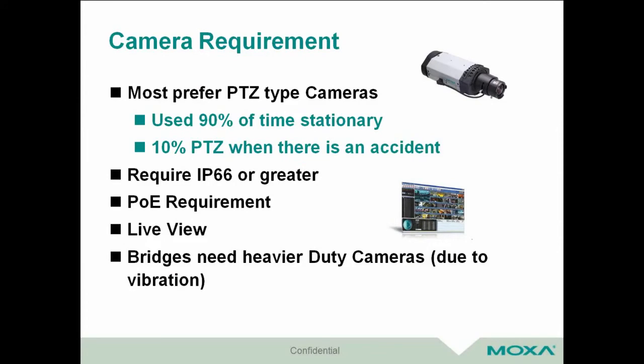That's where you're put in a gray area where you really want to focus on, okay, if I want to put on a camera, will I go with something that's not a standard, or can I live with that and probably migrate into something later? But keep that in mind when you're dealing with PoE and cameras, because for the high-end power PoE there's no standard yet. The standard PoE, the 30-watt, 802.3at and af, is kind of more or less where the lower end power is, and that's pretty much basic for most cameras out there.